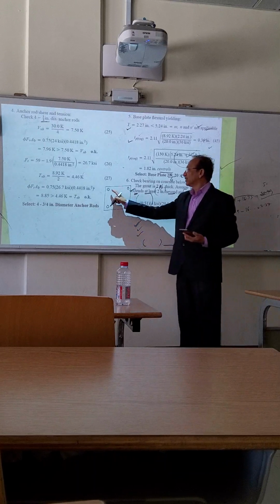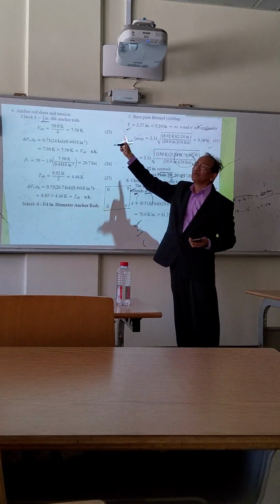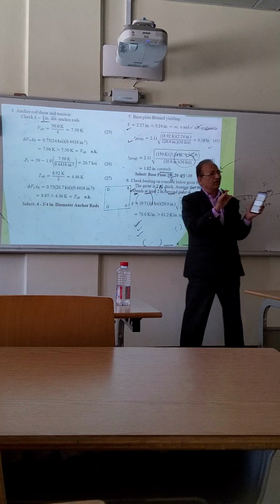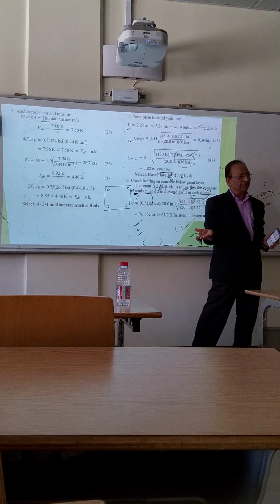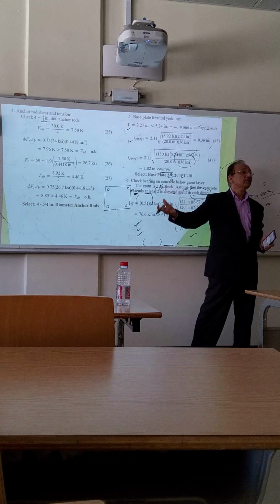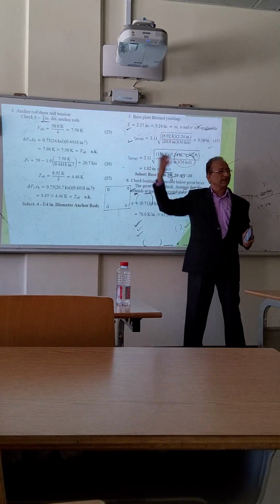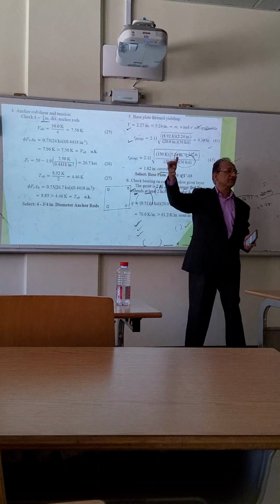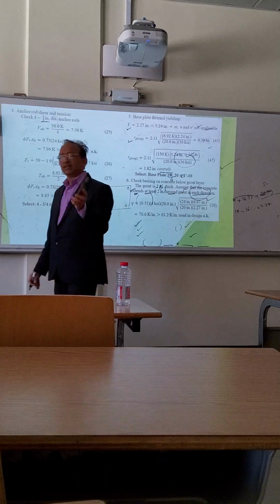So if 4 bolts are the minimum requirement and I am taking 3/4 inch, if this 3/4 inch is sufficient, I will continue with this. If it is failing, I will have to change the diameter. I say okay 1 inch. If 1 inch is also failing, I will take another diameter, 1 1/4 inch, like this. Okay, because design is trial and error.